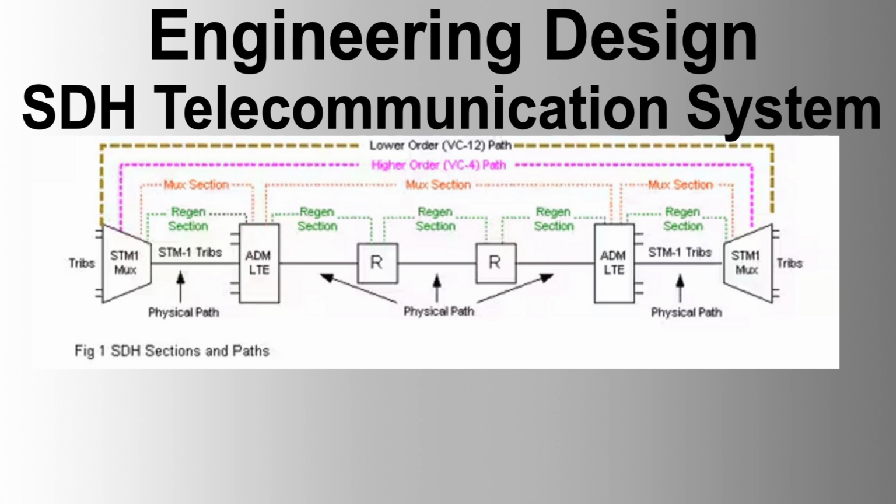Equipment layout. Standard cabinets. All telecom equipment shall be mounted in standard communication cabinets with louvers and fans for ventilation. Cabinets should be equipped with slide rails/trays and swing door frames for easy access. Patch panels. All copper and fiber cables shall be routed to suitable patch panels for access, and all panels should be intelligent type with monitoring systems integrated with the NMS. Grounding compliance. Grounding of all cabinets, racks, and chassis of enclosed components shall comply with industry standards.